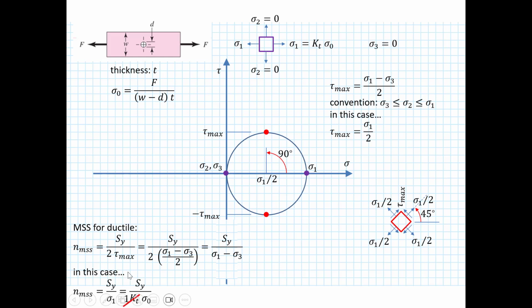And the thing in the book, it says, hey, if it's a ductile material, we treat that KT as 1 for the purposes of determining our factor of safety. So that's a very nuanced discussion. Remember, the stresses are there. That sigma 1 is there. It's red like I showed you. But since it's strain hardening, the book says to go ahead and treat that KT as though it's 1. They call it unity, same thing.